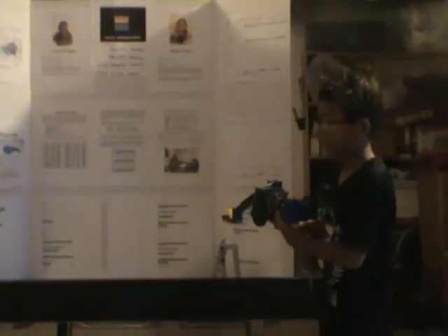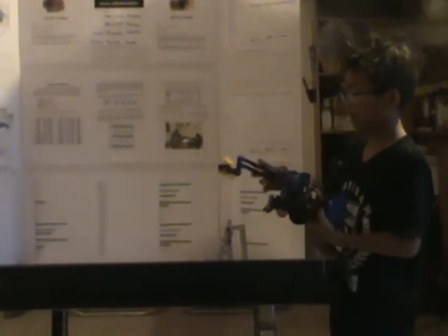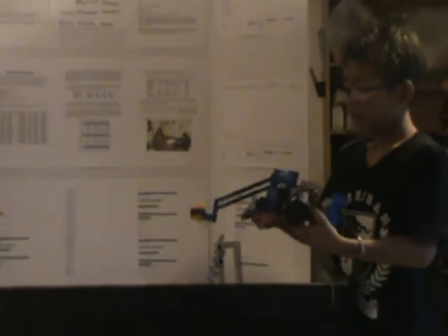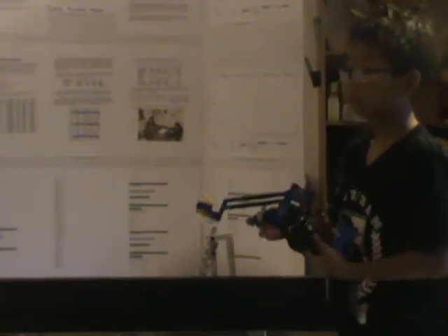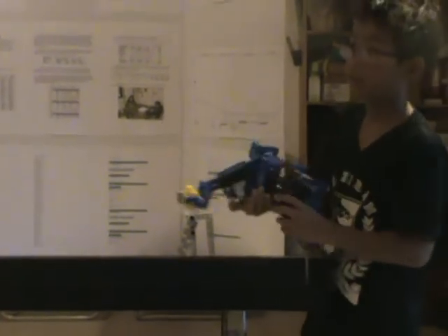And these are the highlights of the robot's design. We have an extra line follower sensor in the back. We also have a counterweight in the back to even out the weight from the front. If we did not do this, it would go up and down and tip forward and down, and we cannot count the ticks correctly.